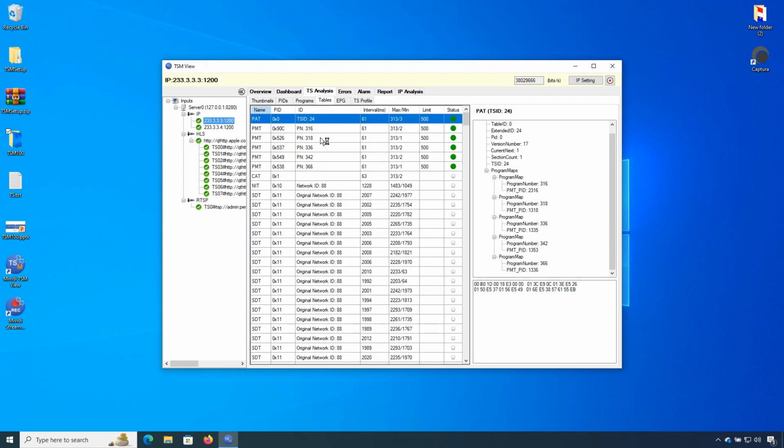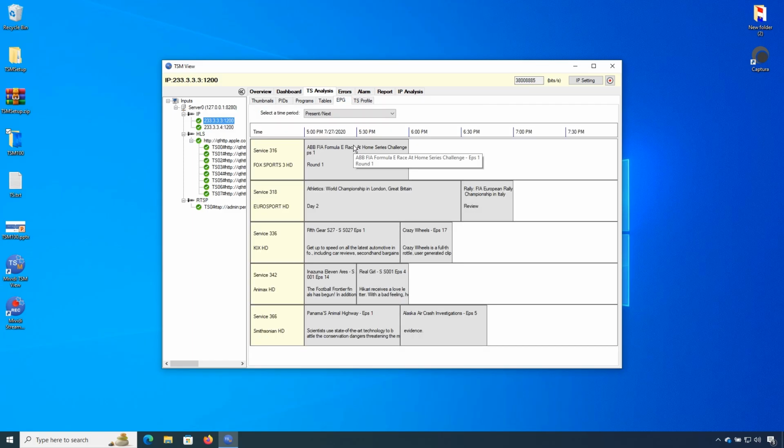The TSM100 will monitor and decode all PSI, DVB-SI, and ATSC-PSIP tables. The table intervals between two consecutive tables are measured. All tables found in the TS are shown in the Tables tab. TSM100 displays the EPG information similar to the way that is displayed in a consumer's TV.